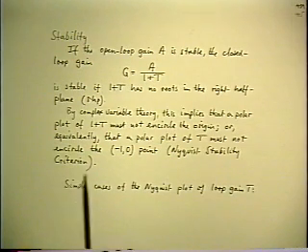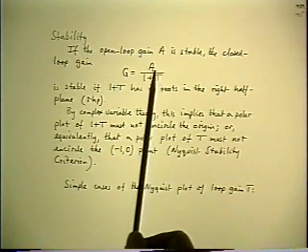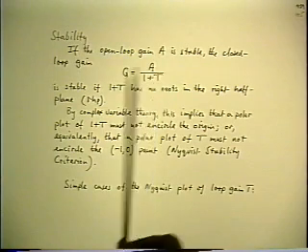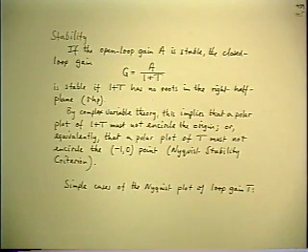So let's make the usual simplifying assumption that the open loop amplifier itself is stable. You might say that's not much of an assumption, because if by definition it doesn't have any feedback, how could it be unstable? Well, that's true, but you have to remember that there's all sorts of feedback effects which are inherent in your amplifier that you may not have put there on purpose, because there's things that you can't control.